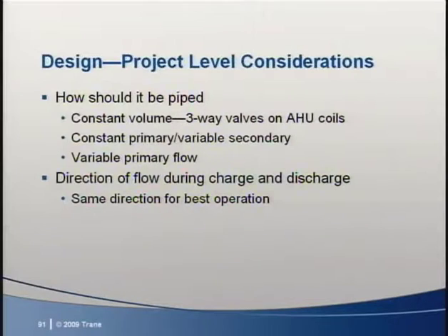Another question that comes up a lot is, what system architecture should I use? All configurations are theoretically possible, but some will be much simpler than others. If you elect to vary the flow through the chillers, you'll have to consider new flow limitations as the temperatures change in the system between charging and discharging modes. Some of the commonly held positive and negative aspects of each system are amplified or minimized.